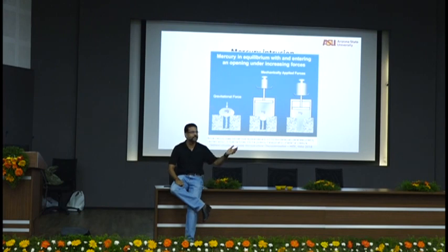And if you remember your structural engineering from somewhere, there is something called strain compatibility that you have to satisfy in any mechanical loading, which you are never satisfying because your 200 gigapascal stiffness plate is pushing a 40 gigapascal stiffness specimen. That too, the older compression machines are pushing only from one side, not from two sides. Again wrong, because the equilibration of pressure on both sides will take some time, before which microcracks would have formed. So that's why you see different labs will give you different results. All of these variabilities.